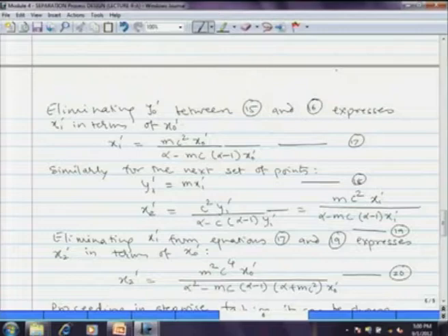x1 dash is the composition of liquid on the first plate, and x0 dash is the composition of the liquid which is being obtained as distillate. It is the same as y1 dash, okay, because the same vapors condense, but x1 dash is different.